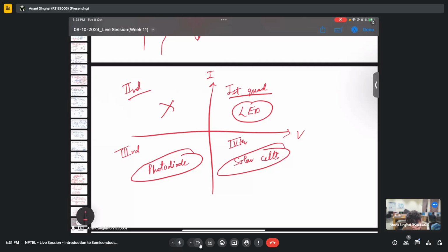Okay, so what it is saying is, the photodiode always works in reverse bias, as compared to the solar cell, which works in both forward and reverse bias. The photodiode is basically a PN junction diode operated in reverse bias. When an optical signal is incident on it, the depletion region separates the photo-generated electron-hole pairs and produces an electric current in the external circuitry.